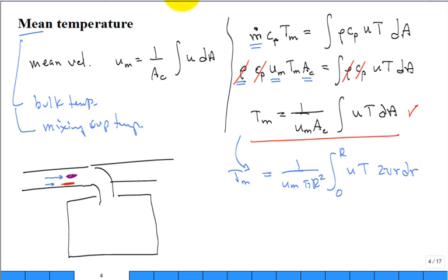that's well insulated, let that fluid mix, and you're just grabbing the whole package of fluid for an instant of time, let that fluid mix, you'll get a temperature that's uniform throughout that mixed cup. And if you measured that temperature with the thermometer, that temperature would be the mixing cup temperature, which is the same as the bulk temperature, which is the same as the mean temperature.